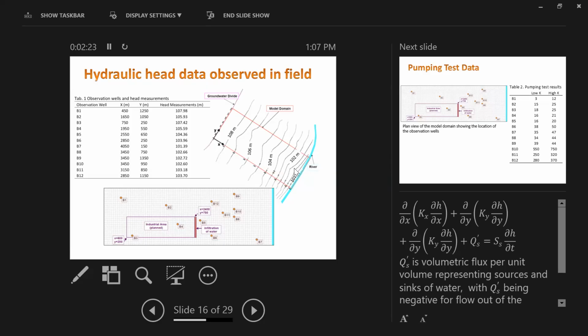So we have a river here. The river recharge is a source term; it adds water to my system. The river can also take water from my system. Here the head of the river is 100. If the head in your aquifer is higher than here, then water will flow from your aquifer to the river. If the head in your river is higher than your aquifer, then water will flow from the river to the aquifer. So basically, we have what is called head dependent flux. Depending on the head, you will determine the magnitude and the direction of your flux.